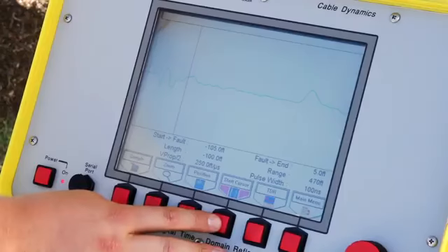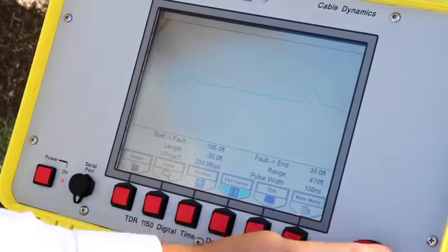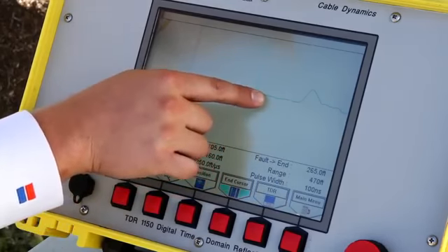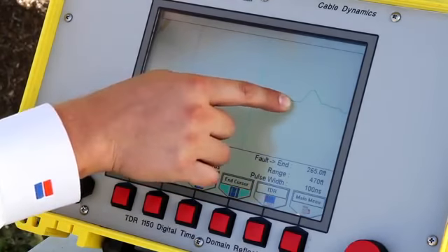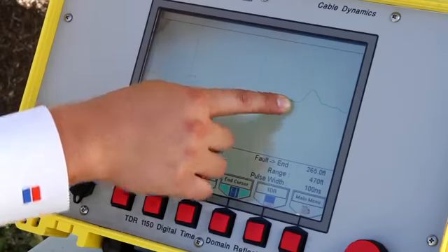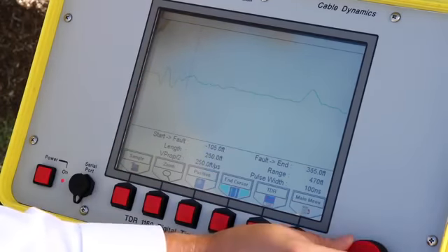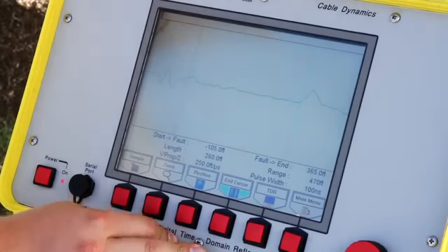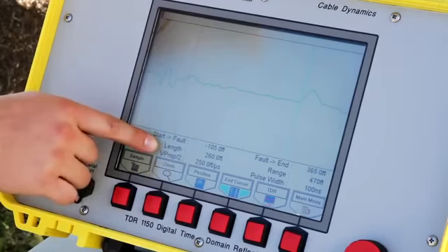So we'll hit the button again, adjust the end cursor, and scroll it out using the red rotary knob to the green line, which indicates the low voltage TDR, where the positive inflection, which signifies an open, begins. We'll scroll that out to the beginning of that, because that will signify the end of the length of our cable run, which is displayed on the screen here under length.